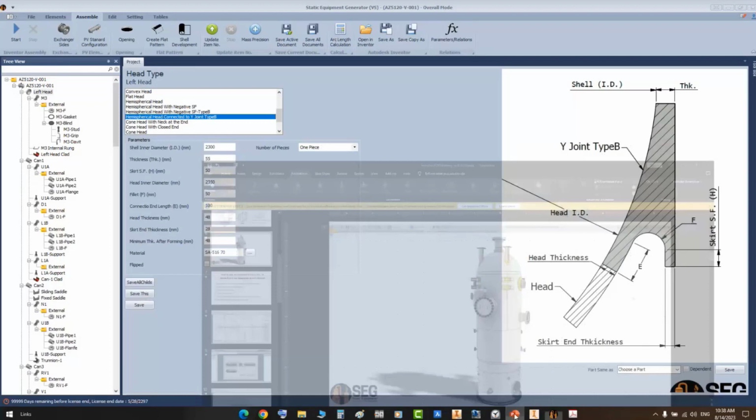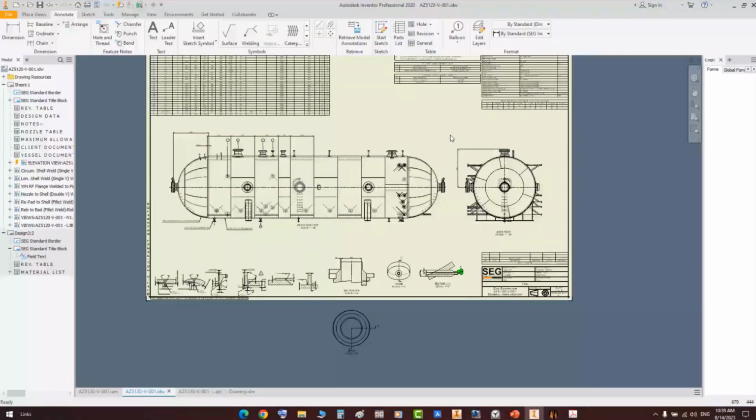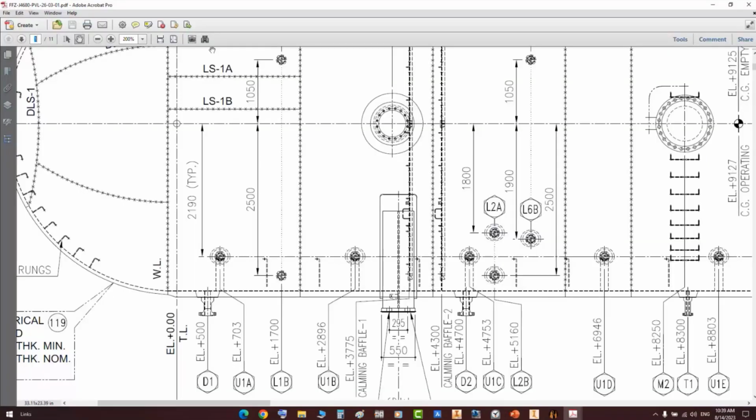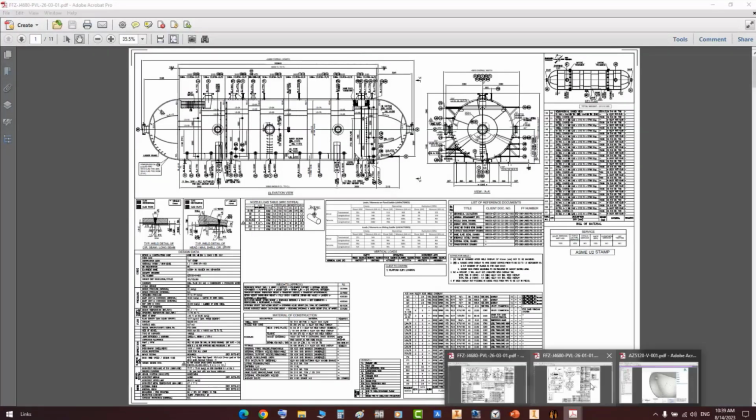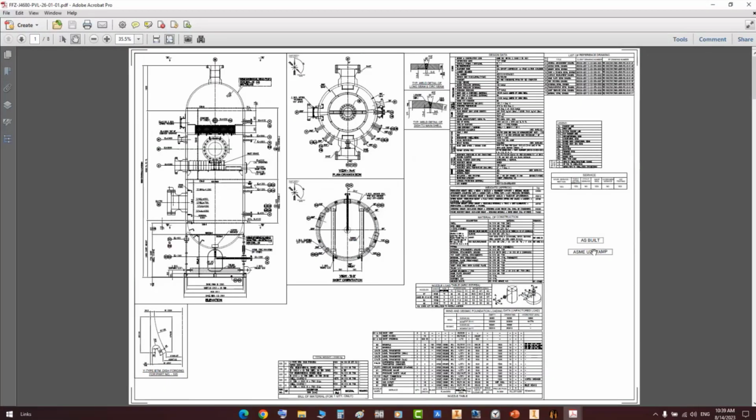I think now we have covered some of the important points related to the received drawings from your side: how to generate the 3D model, how to add non-standard items to the model, how to generate a sub-detailed drawing, and we did that with the saddle detail, modifying it by adding fireproofing. Also how to generate a forged hub, how to edit it and measure the distance of this forged hub, and you can use that to generate G-code for it.